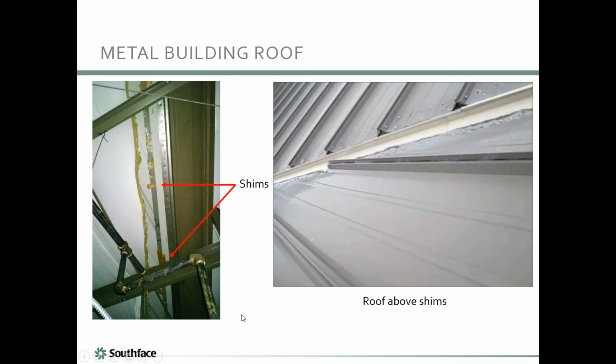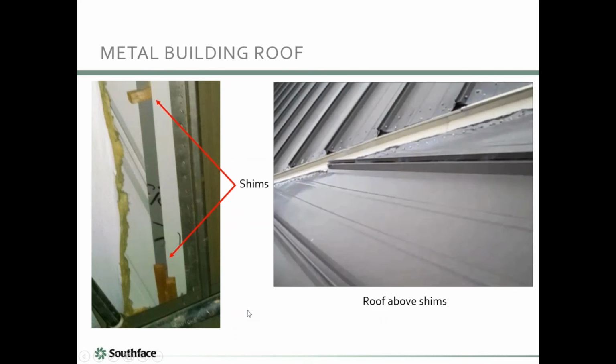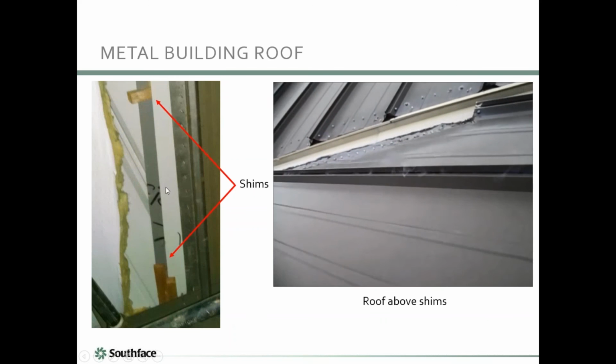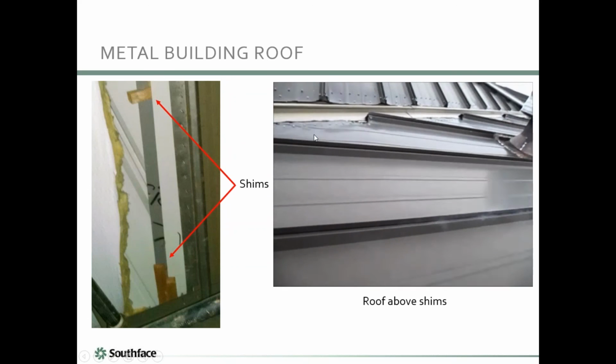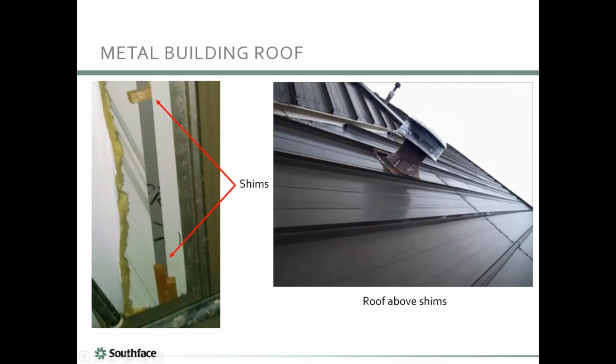And to do this test, as you mentioned, we pressurized the building, probably to about 75 pascals or something, a pretty high pressure. There's nothing magic about the amount. The higher the pressure, the more likely you are to see the leak.